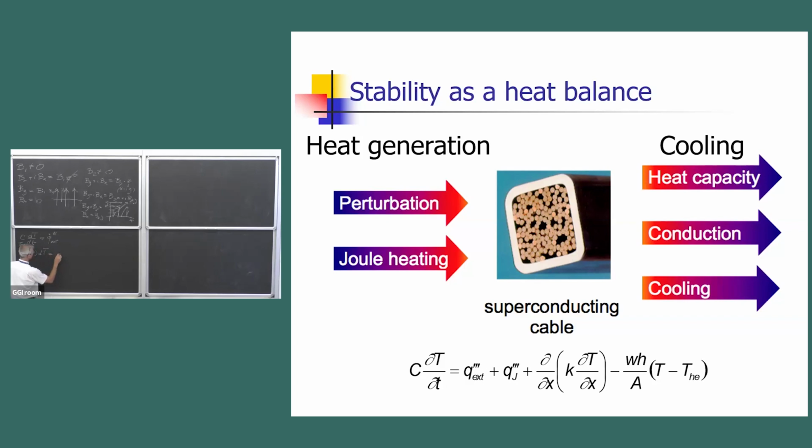So this is equal to the integral of the external source, say from 0 to infinity. Infinity means the end of the heat input, okay? So this is the volumetric heat that goes into the superconductor, and the integral of the heat capacity in temperature is nothing else but the enthalpy. That's the enthalpy of the superconductor, or volumetric enthalpy.